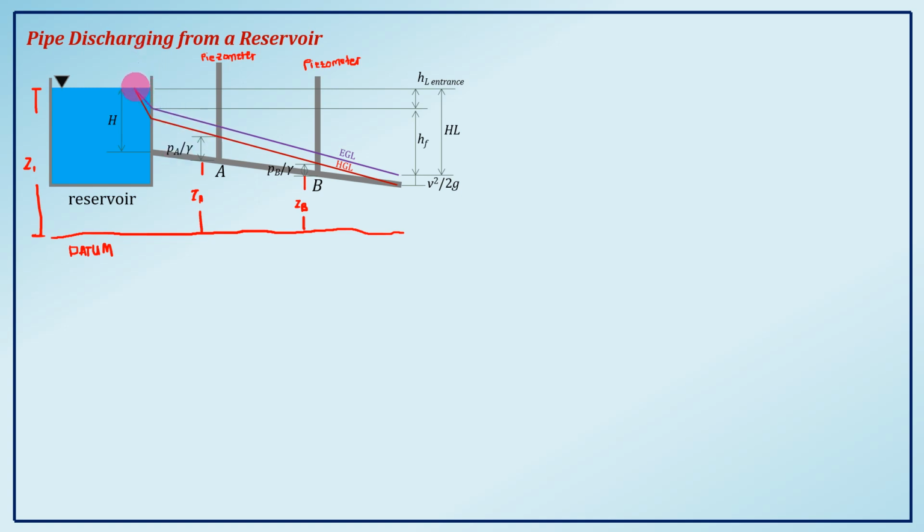From the surface of your reservoir, we have a certain drop of the HGL due to the head loss, or pressure head loss, at this point where the liquid enters the pipeline. That is what caused the drop in our HGL, so our pressure head went down here. The HGL is your pressure gradient, so it plots where your pressure head is. At this point, the pressure head locates here.